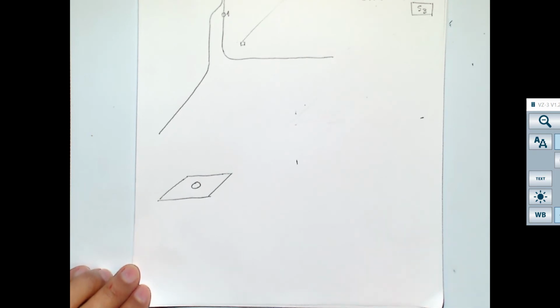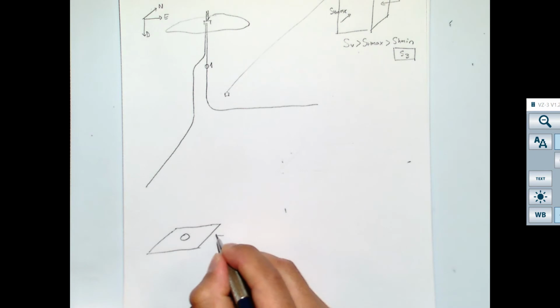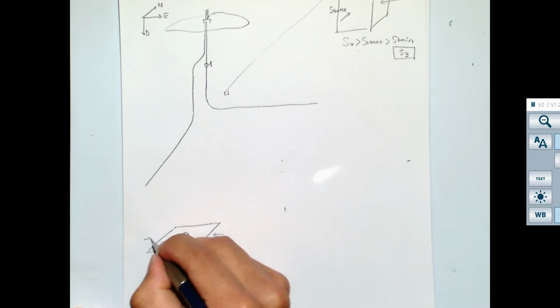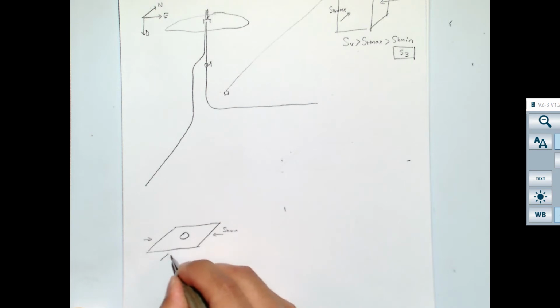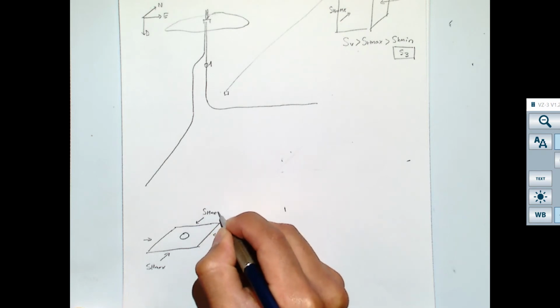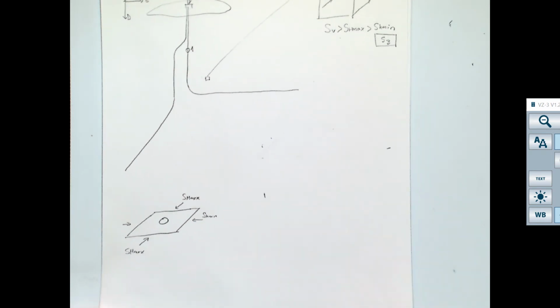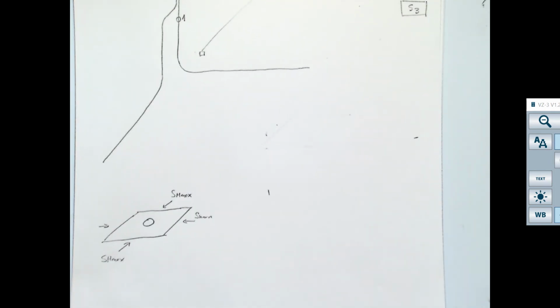And according to these conditions, I have SH min coming east-west and SH max coming in direction north-south. My question here is, where are you going to see the breakouts? Tell me.